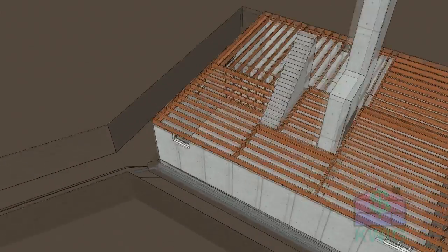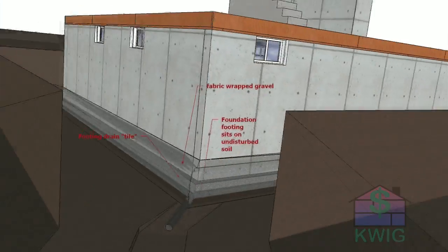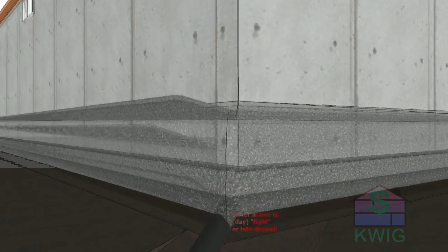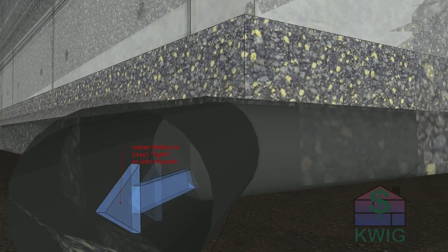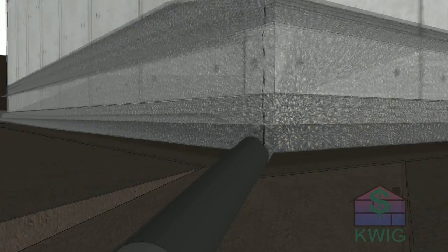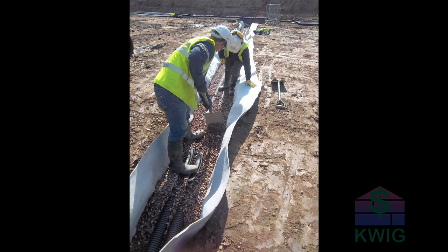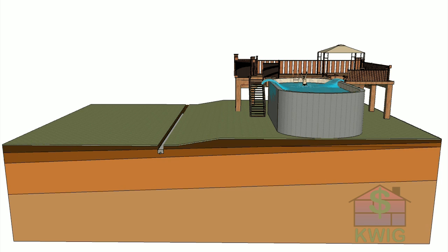These days, it is recommended that homes are built with gravity drain pipes installed around the footings to redirect water away from the home's foundation and not let it pool by the house. Generally, you can combine all the drain pipes or tiles in one trench that will carry them to daylight or open air that is downslope of the origin. But there are other ways to control groundwater.